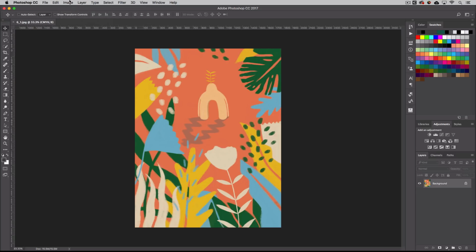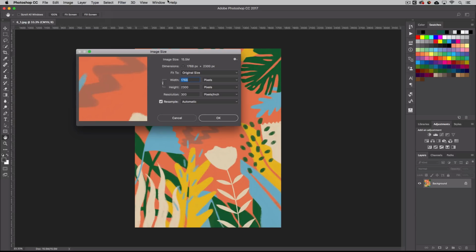The other major important thing is to make sure that the image size is at least 300 dpi and not a 2x2 thumbnail. So for this example, it's almost 6x8 in size at 300 dpi. And what we'll want to make sure we do is when we import this image into InDesign that we don't scale the image up, because we all know when we scale an image up, it actually pixelates that image and prints with little square patterns in it.